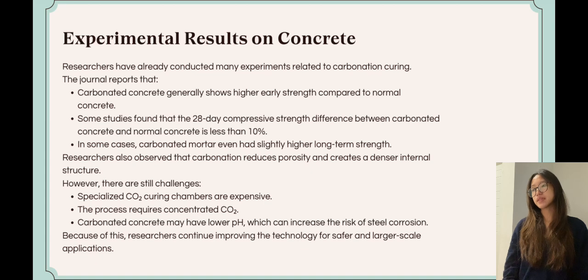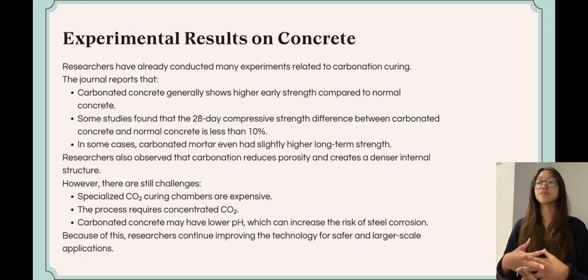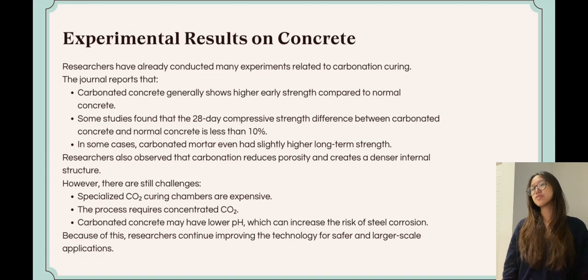Experimental results on concrete. The researchers have already conducted many experiments related to carbonation curing. The journal reports that carbonated concrete generally shows higher early strength compared to normal concrete. Some studies found that the 28-day compressive strength difference between carbonated concrete and normal concrete is less than 10%. In some cases, carbonated mortar even had slightly higher long-term strength. Researchers also observed that carbonation reduces porosity and creates a denser internal structure.